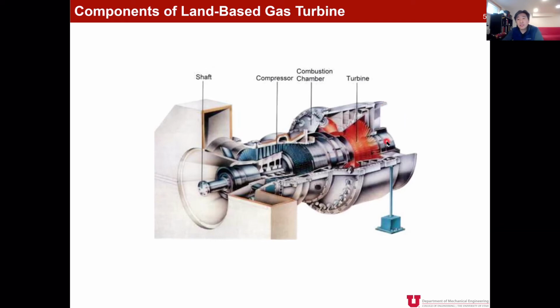And this rotation in the turbine, basically connected with the shaft, also runs the compressor. So the compressor's operation and power comes from part of the power generated by the turbine. And the difference, the excess power after we run the compressor, actually should go to the generator, and this generator generates electricity. So that is how we make use of a gas turbine to generate our power.